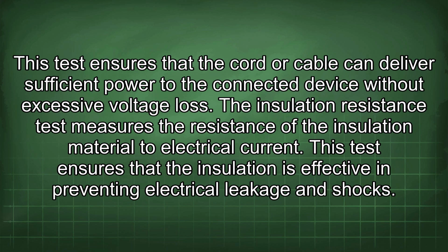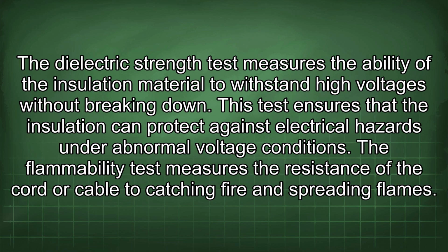The insulation resistance test measures the resistance of the insulation material to electrical current. This test ensures that the insulation is effective in preventing electrical leakage and shocks. The dielectric strength test measures the ability of the insulation material to withstand high voltages without breaking down. This test ensures that the insulation can protect against electrical hazards under abnormal voltage conditions.